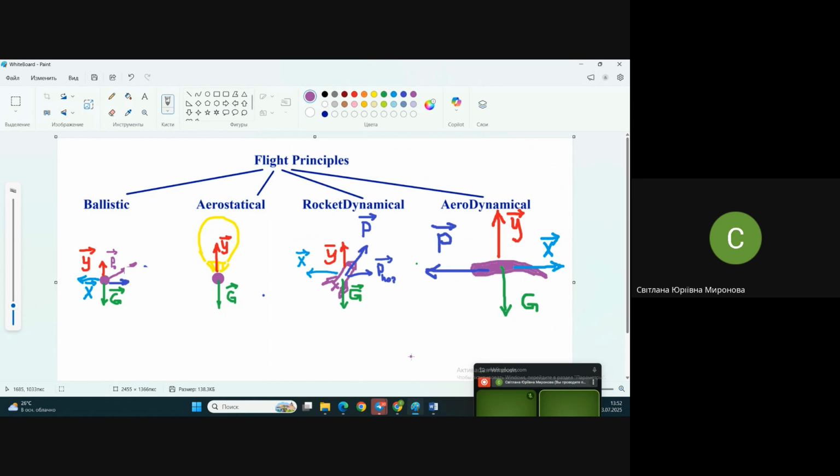Ballistic means someone applies an initial force. If this force is a bit deviated with respect to the horizon, you have a decomposition of the vector of motion, and this decomposition may conditionally be considered as lift and some pushing force which moves the object forward, but it disappears. It is permanently spent during the flight, and as there is no engine supporting this initial energy, the energy is just spent counteracting the drag and the gravity force.